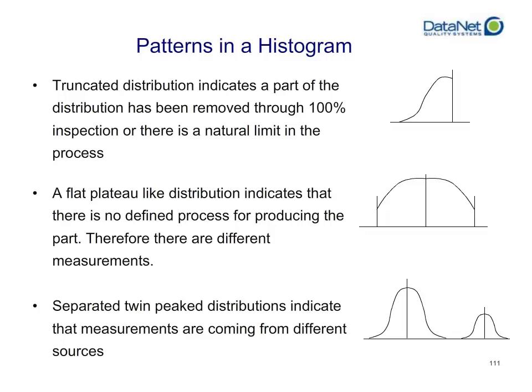Your customer has certain tolerances. You're just not able to produce it at any reliable rate, and you're almost lucky to, or you need 100% inspection to find the good ones amongst the bad ones. If you're shipping everything, regardless of actually checking this, you're probably giving your customers hit or miss on the quality of whether or not it even meets their specifications.